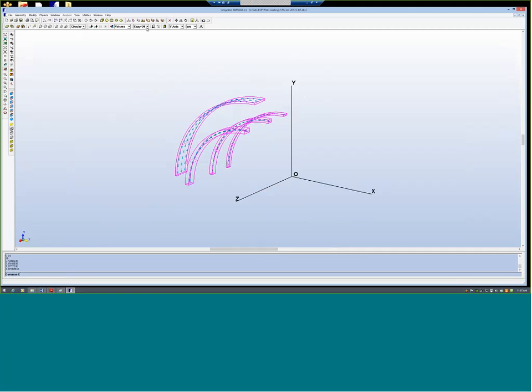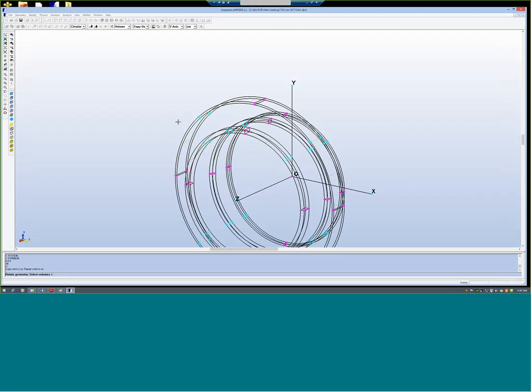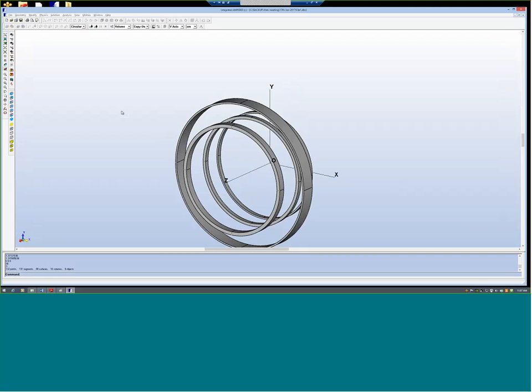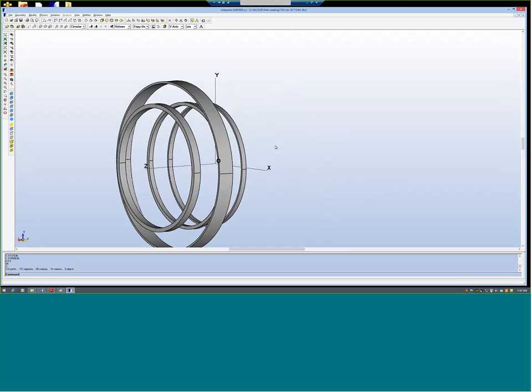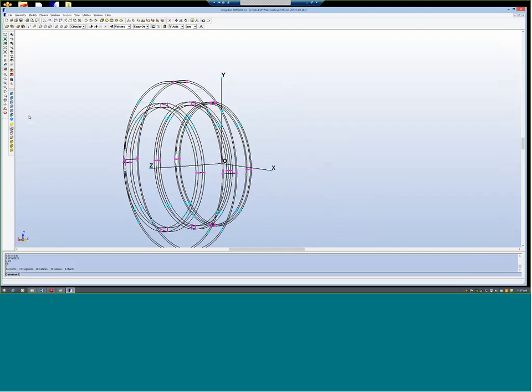Now what I do is I will turn copy on, and also this repeat button. Then you rotate this 1, 2, 3, 4. So 0, 0, 0, the Z-axis is the rotation axis, 90 degrees. Repeat value is 3. So now you can see here that this half of the coil sections are completed, and if you go and see all the attributes, the volume current attributes are complete.